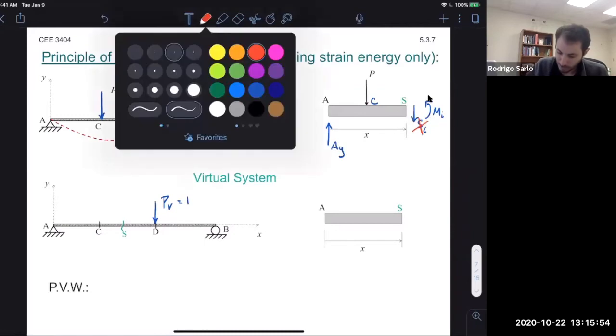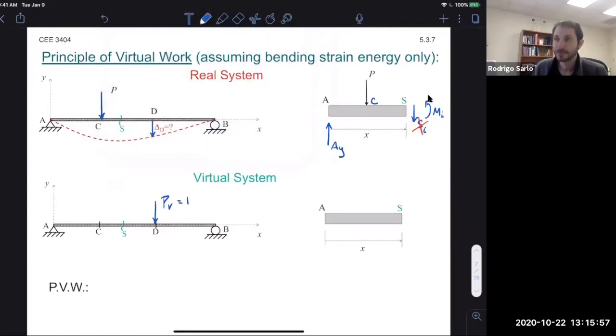I told you we weren't going to worry about shear, so we're not going to worry about it. Just ignore it. We can solve directly for the moment, right? We don't need to solve for shear if we're using the equation method. So simply, we use this. We'll do a more concrete example in a second, but I'm just walking you through the procedure.